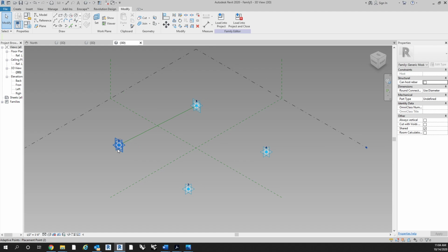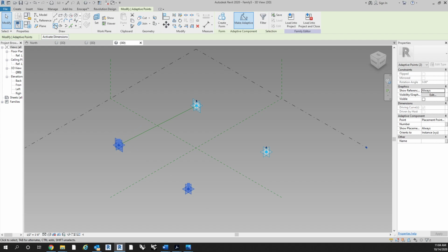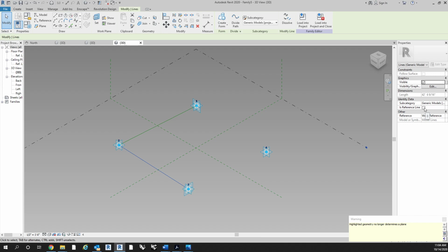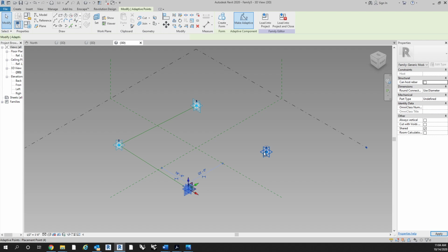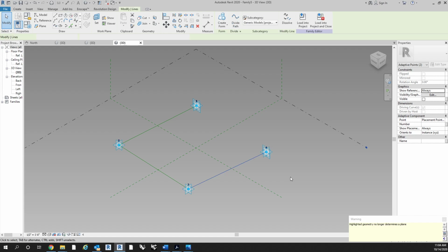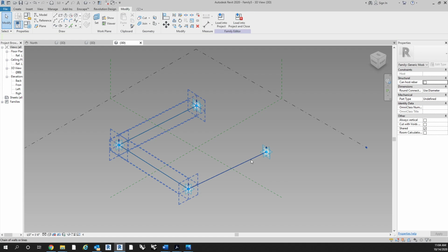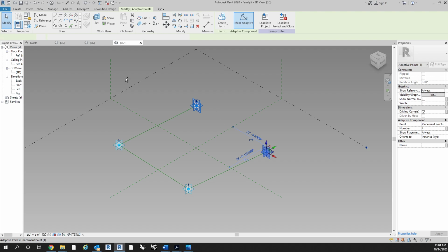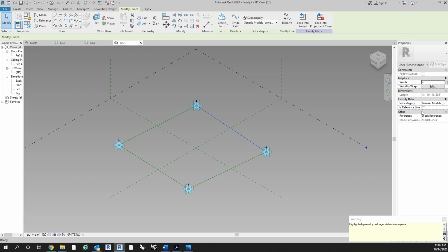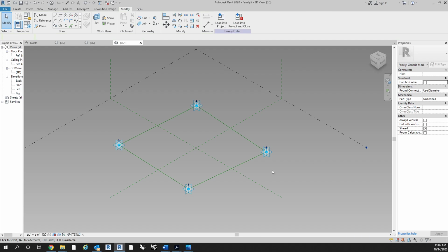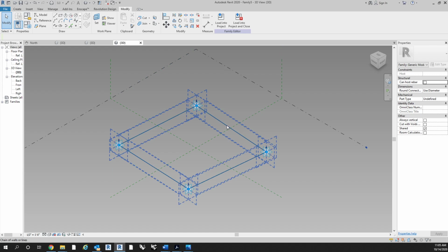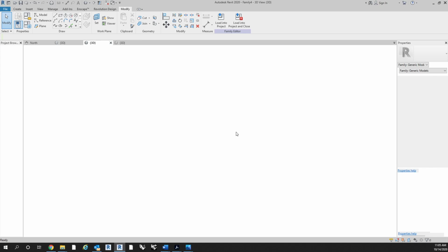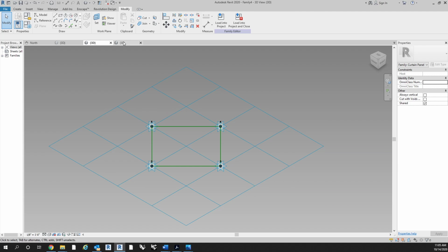So do that for the corresponding 3 lines. Spline through points, is reference line. If you deselect for whatever reason, just make sure that you tab into that specific line and just hit is reference line. And then one more time, and we're all good. So now we've basically recreated this guy, right?